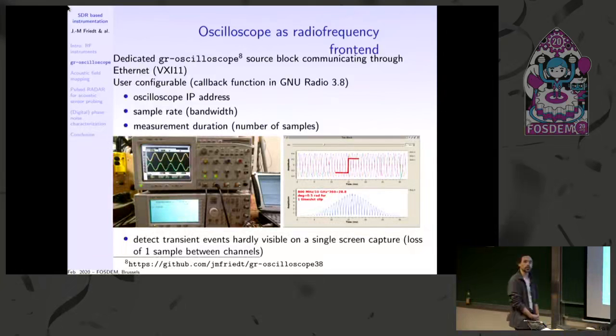Actually, the funny thing is we realized we did not have these kinds of jumps between channel 1 and 4, but between channel 1 and 2, we are losing some samples. Don't ask me why. But that's way out of specs of the scope as well, right? Why is it? Well, this is a 10 gigahertz sampling, sorry, I must have misspoken. This is a 10 gigahertz oscilloscope with an 800 megahertz sine wave output. This is one that I captured, but this is the kind of thing that you see jumping. If you trigger on the phase, you see this jumping once every second.